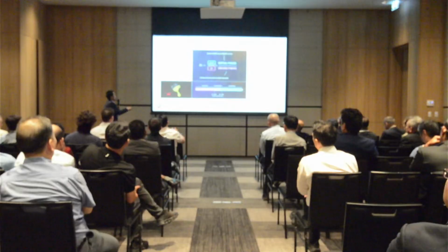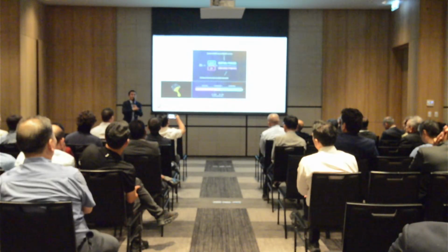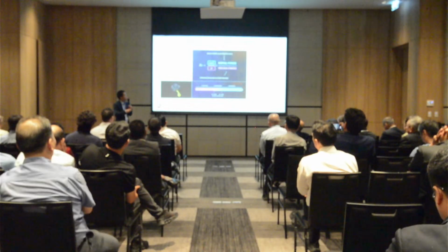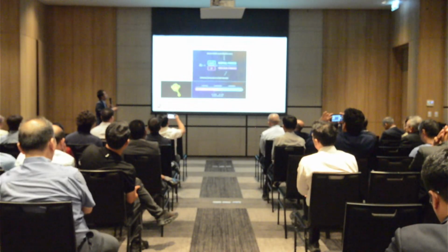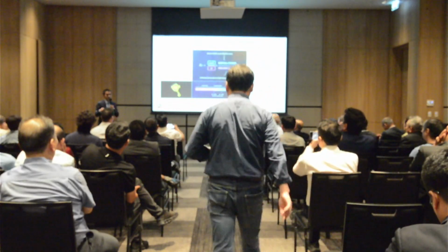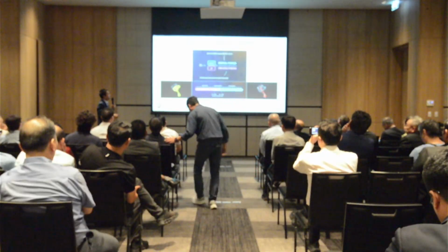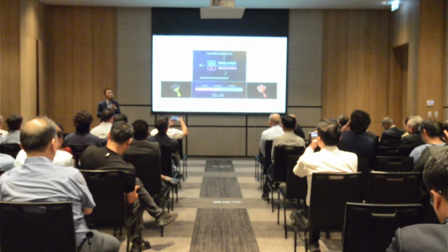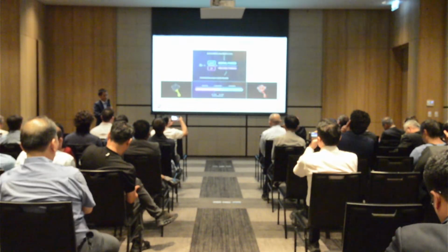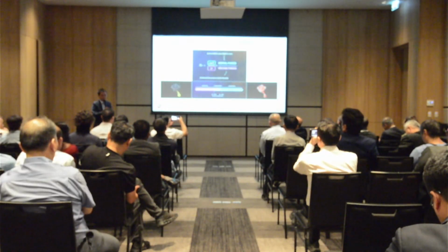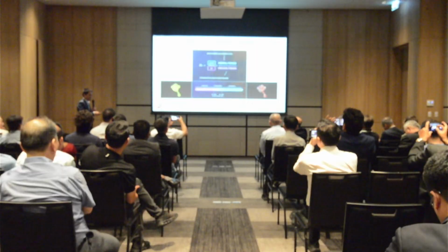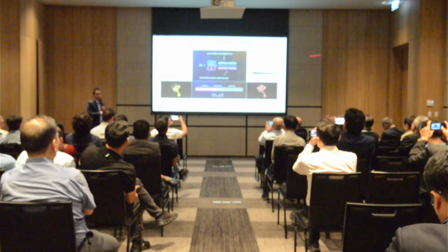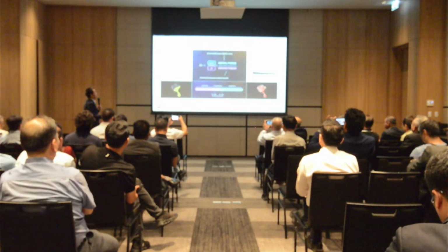Squeeze casting, gravity casting or low pressure casting, all have very low gate velocity. That's why gravity casting, low pressure and squeeze all have laminar flow. But for die cast, it's turbulent flow, because the gate velocity is about 40 to 60 meters per second. It's turbulent. Why? Because velocity is high. That's why you will have porosity for sure, gas porosity.